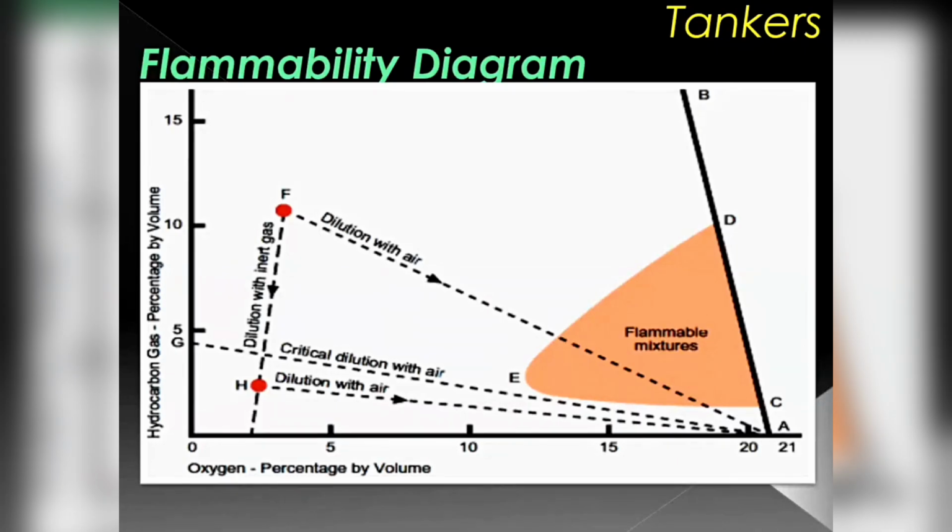Okay, if we have a cargo and we know its LFL and HFL, can it depend on the volume of the cargo? Can the volume increasing or decreasing define the HFL and LFL? See, it depends on the percentage of the gases which are present in the cargo. For that particular cargo, it will not change. The limit will remain more or less the same. But most cargoes have a mixture of a lot of gases.